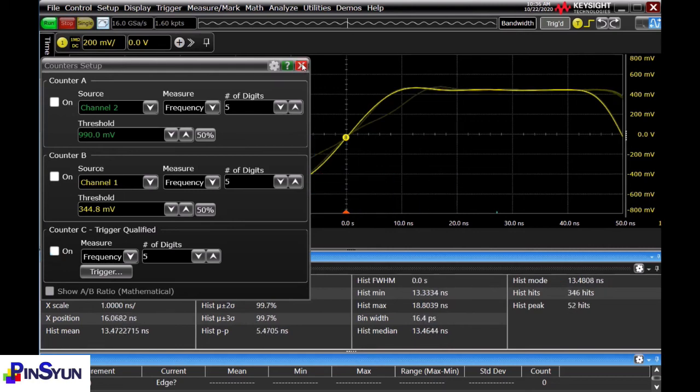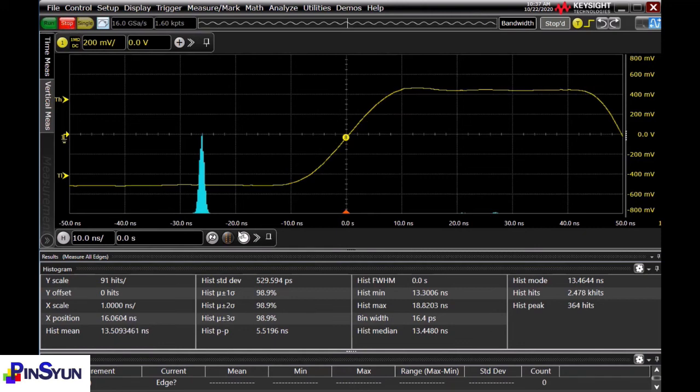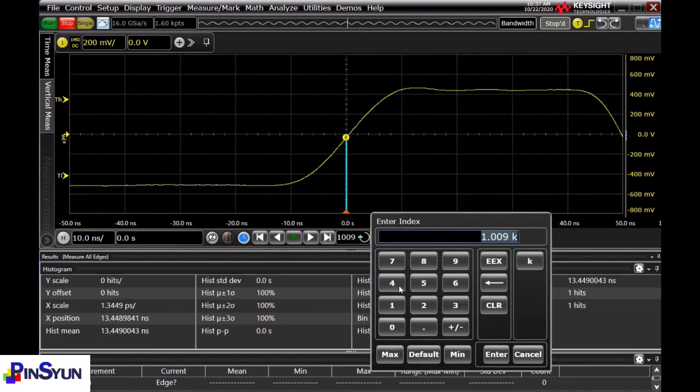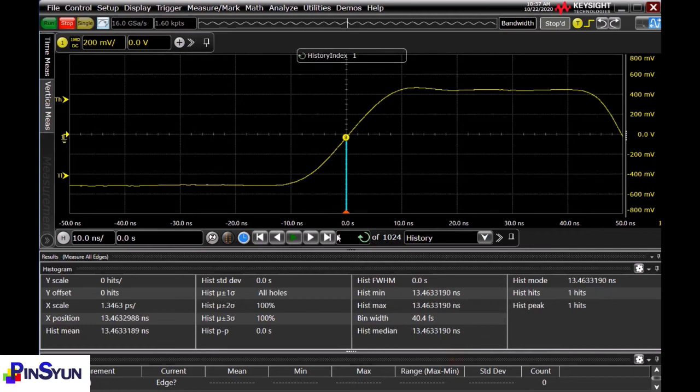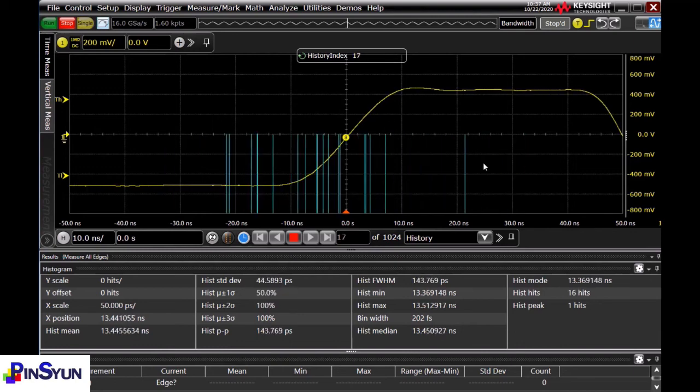And then the next thing you can actually show is the built-in history and segmented memory. So this is demo 5. So we'll start with the history mode. Pretty easy. So you just click stop, and down here with this little clock, you can navigate through the past 1,000 captured faults. And what I can actually do here is say, reset this back to fault number 1 in the history mode and just click play. And it will play through all 1,000 of these events.